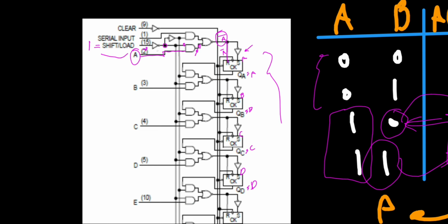So this 0 would also cause us to have a 1 here, and the serial input, which I call S, we have S and 1. And based on the truth table of the AND, again, the output follows the other input. So we would have S here, which therefore causes us, let me just wipe these things out.